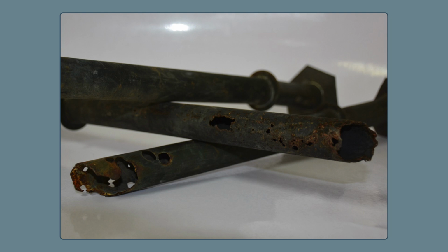That's fascinating. A lot of our work at Mintek has gone into trying to look at this mechanism and explore alternatives for use in these types of environments. I know we have a team that is looking at new alloy development for these areas, looking at additions of other materials, chromium, aluminium, silicon, sometimes copper, to control this or retard the metal dusting reaction.